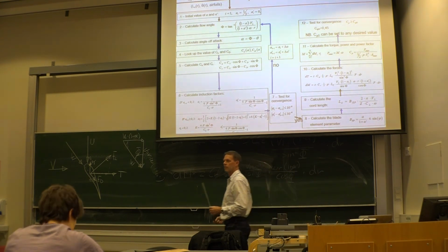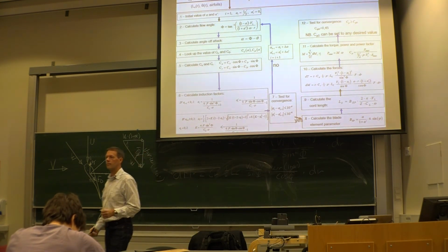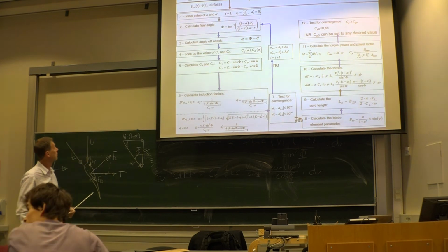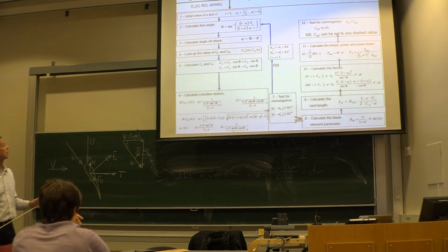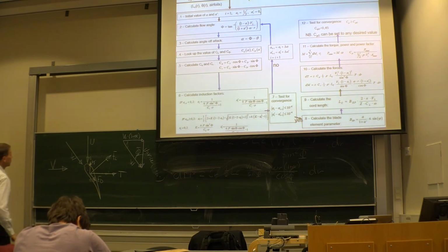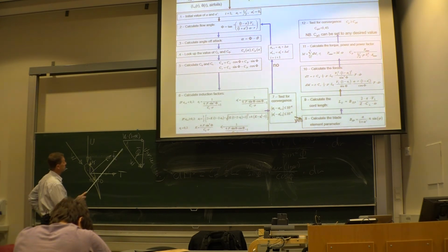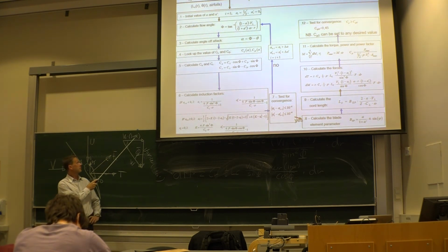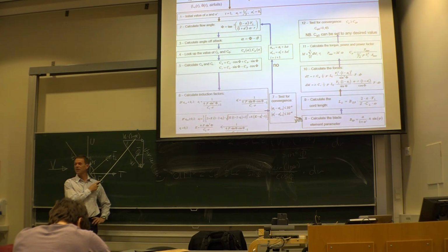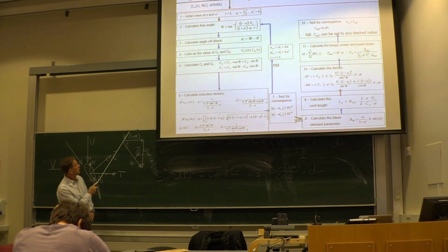In step 3, when you calculate the angle of attack, how do you know the twist angle theta? Do you take the first one? You have the velocity of the wind far upstream. Yeah, you have guessed that one in step 1.